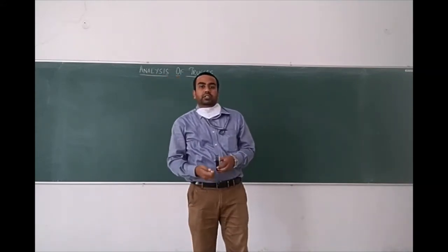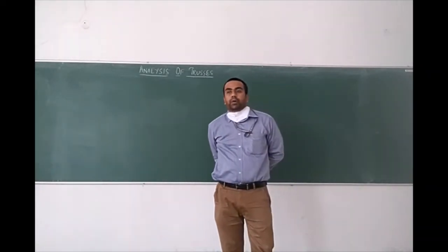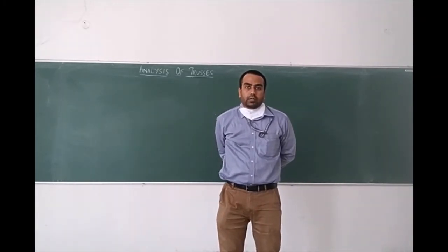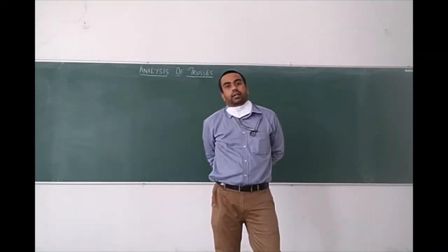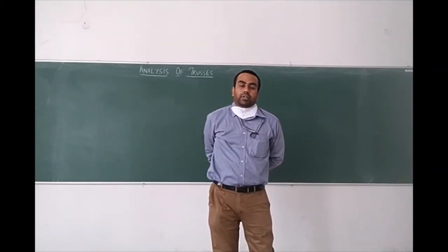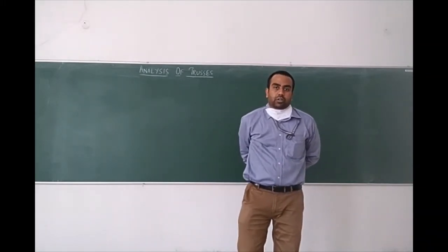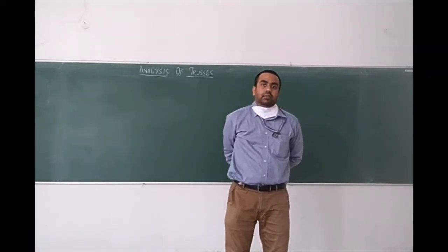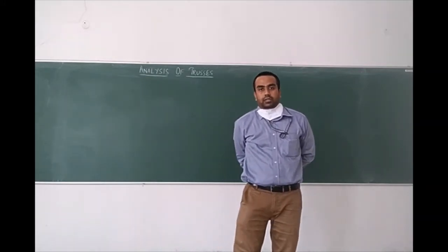So what are truss elements? Truss elements are again load bearing elements, but these truss elements, though they behave as one unit, they consist of number of beams which are connected at their endpoints. We call those endpoints as joints, and we assume that the load acts only on the joints, and if there are any other particular forces acting, we consider it to be axial loads. We don't take into consideration the bending loads for trusses.